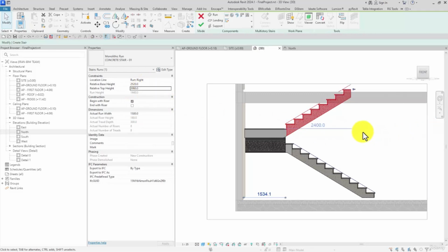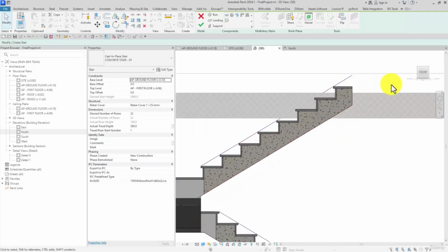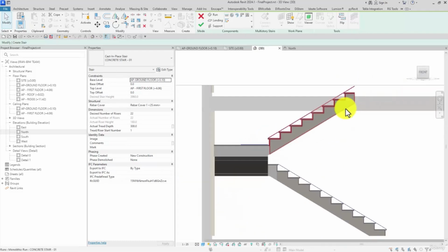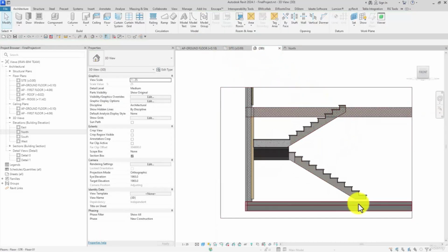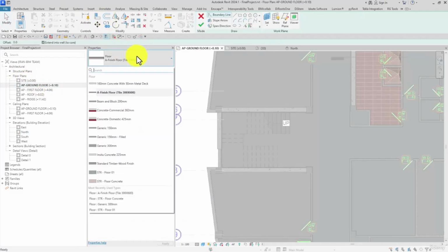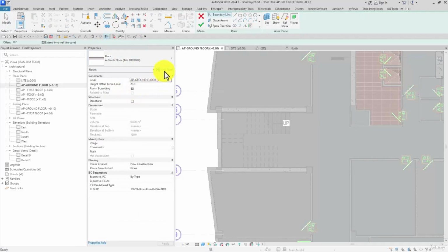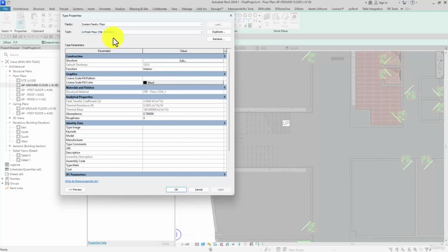and 3960. Right now this is correct. And still here we got a gap because of the finished layer of the floor that is not done yet. Then for showing you these parts, I open the ground floor 10 centimeters, then I pick the floor, then I select one of the default floors, a 10 centimeter floor to fill the gap between the stair and the slab,